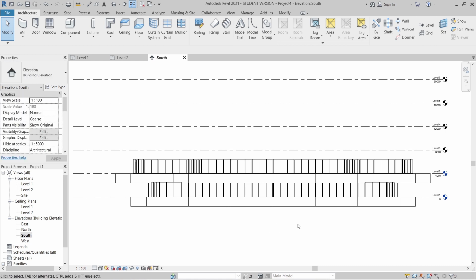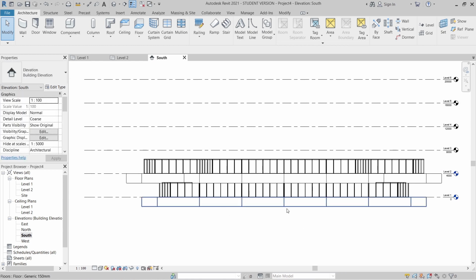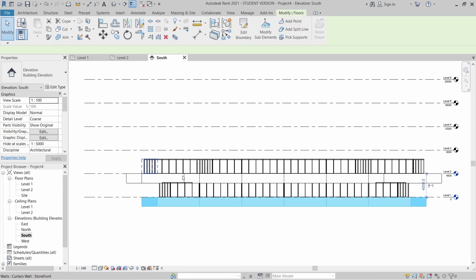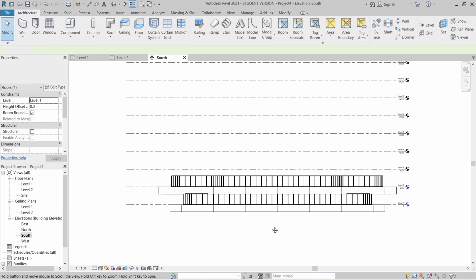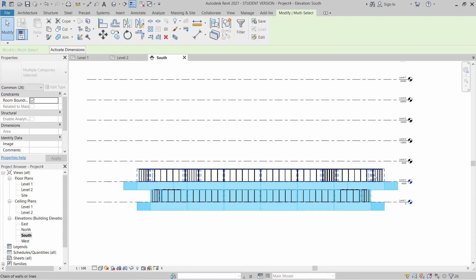Okay, now what I'm going to do next, I'm going to copy. Let me think first. Okay, we select all here like this. Hit the tab key. Here one. Hit the tab key again. Then I'm going to copy all. AR for array. I'm going to array it.